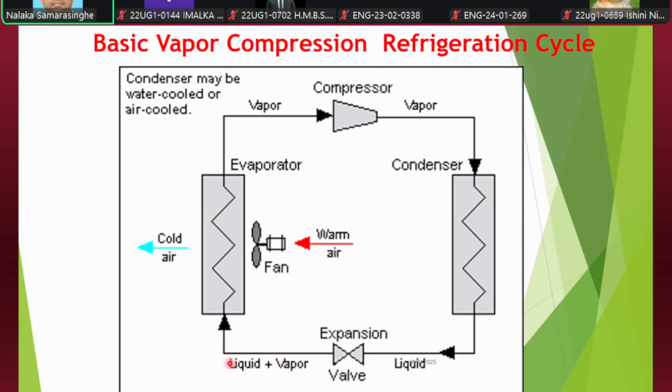When the mixture of liquid and vapor goes into the evaporator, this is the evaporator head that is usually inside the indoor unit of an air conditioner. Since you have some understanding about household air conditioning units, usually split type air conditioning units, inside the indoor unit you have this evaporator part, and there we also have a component similar to the condenser, a copper coil.